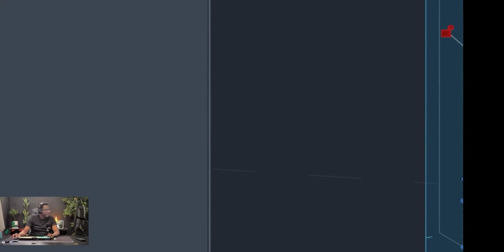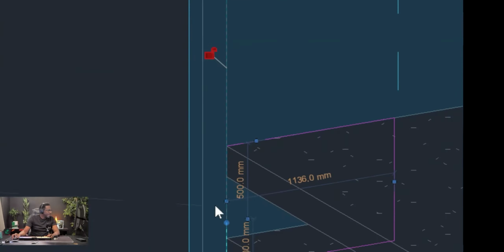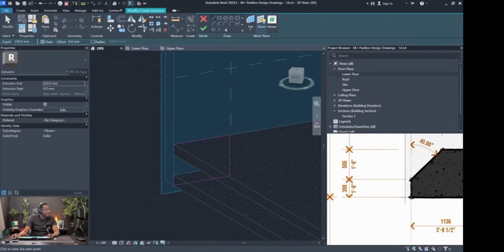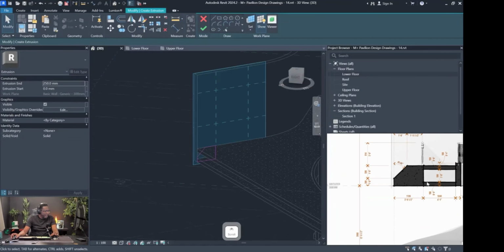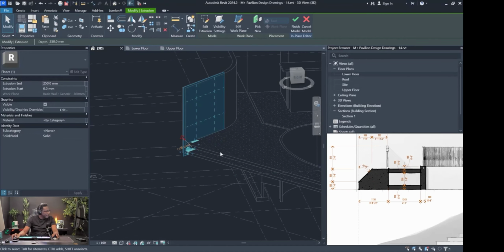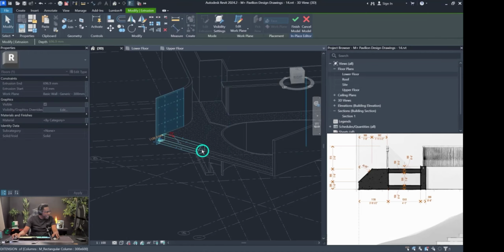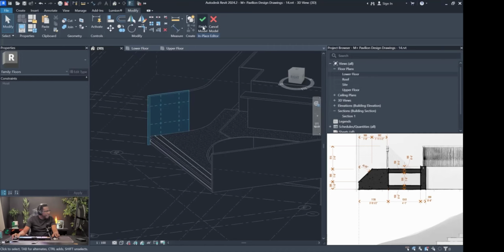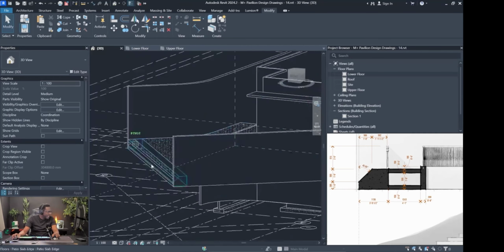That's there. Then we need to carry this up by 45 degrees, and then we will trim this like that. So now we have this shape that's here, and we choose OK, and we need to extrude it all the way to this side like that. So then we choose OK to finish that sketch.